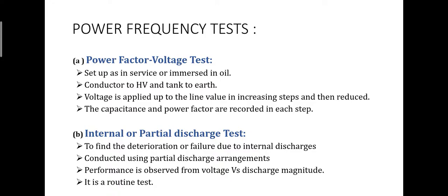And we go to the internal or partial discharge test. This test is to find the deterioration or failure due to internal discharges. It is conducted using partial discharge arrangements. Here the voltage versus discharge magnitude gives us the performance observed. It is also a routine test.